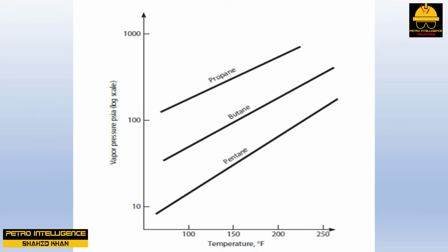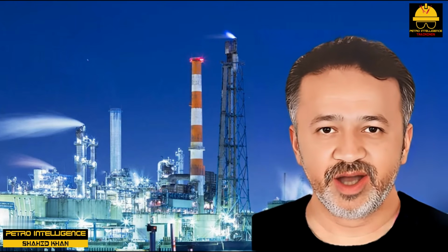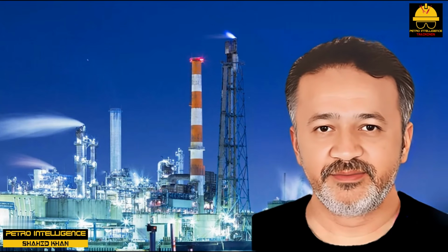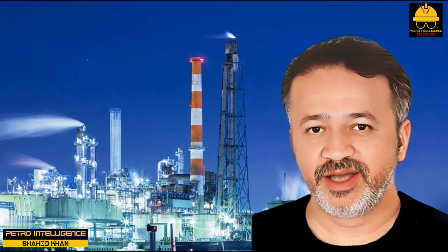Unfortunately, subcooling a liquid is difficult. This means that the heat transfer coefficient for subcooling might be 30 BTU per hour square feet degree F. Even though the amount of heat to be removed in subcooling a refrigerant is small, it may require 30% of the tubes in the condenser to do the job. The reason is the low heat transfer coefficient for subcooling as compared to the high heat transfer coefficient for condensation. The tubes in the condenser required for subcooling reduce the heat transfer surface area required for condensation. In effect, the condenser shrinks.